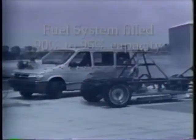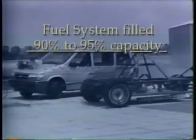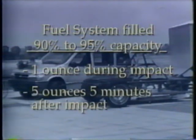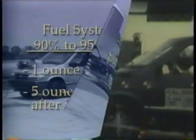A vehicle must also undergo other rigorous testing before it can be sold to the public. For example, to minimize potential fire hazards during and immediately following a crash, regulations state that a vehicle with the fuel system filled 90 to 95% of usable capacity must not lose more than 1 ounce of fuel during the impact, or a total of 5 ounces of fuel during the first 5 minutes after the impact. This specification holds for a 30-mile-per-hour frontal impact into a fixed barrier, as well as in rear collisions where a stationary test vehicle is hit from the rear with a moving barrier.